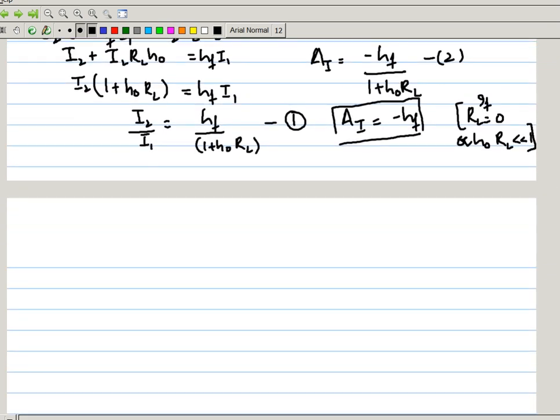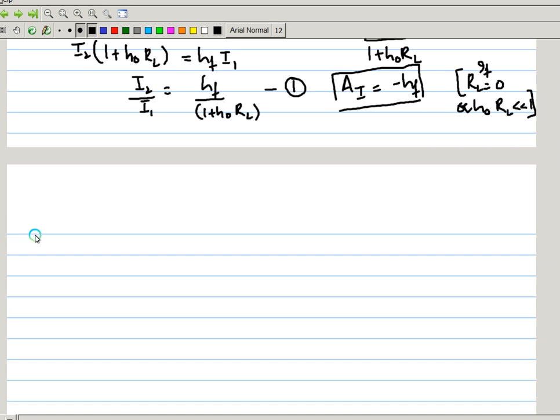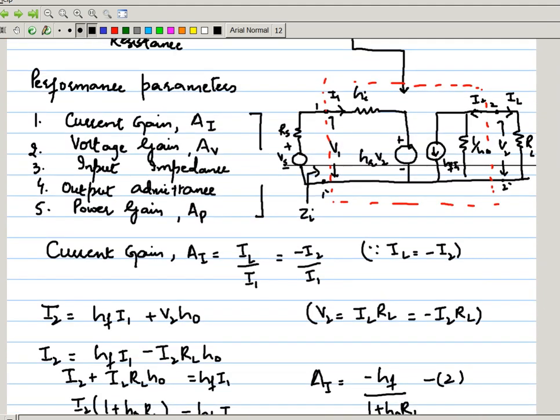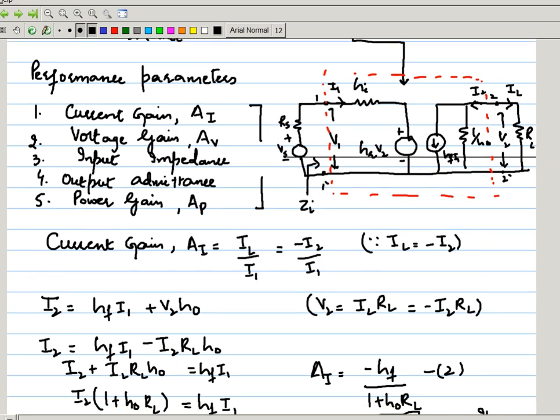All right, so the previous equation will be helpful to us. So input impedance, let us denote it by Zi. Take a look at the input circuit and apply KVL to the input circuit first. So the input circuit where we need to apply the KVL is this. Okay, right.